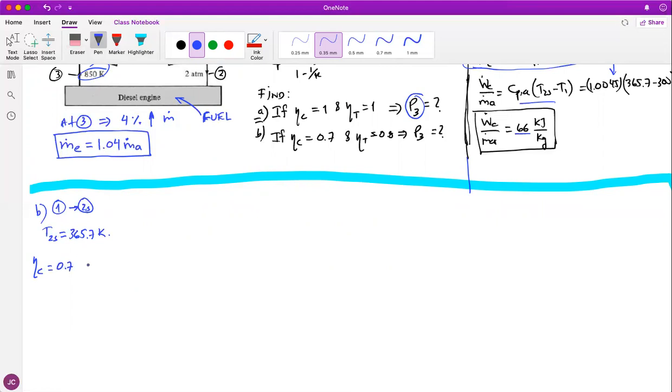So if I have that information over there, therefore I can write the expression for the efficiency, which is work divided by work. I have never known this by memory. I need to always do this, so I will do it again. A compressor always needs to be supplied with more work, so the real part needs to be down there, than the ideal compressor. I'm gonna put compressor, but the ideal part, okay?